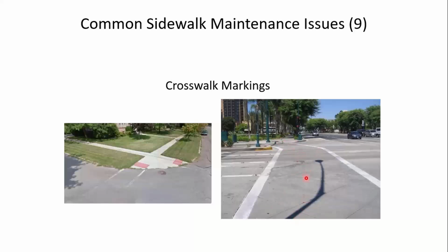The bigger concern here is that this is an ADA communication violation, because the issue is, how does the blind pedestrian using the cane detect that change in direction? And of course, the answer is they are not. Paint is not detectable under a cane tip, and so a blind pedestrian really has no way of knowing that this crosswalk changes direction in the middle of the roadway.